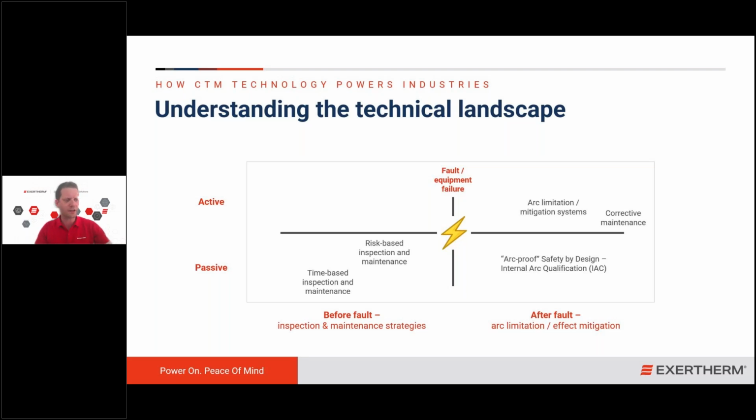And here the discussion circled around the main physical causes for arc flashes. On the one hand, continuous partial discharge sensing, especially on the medium voltage and high voltage side, for identifying any noise or any activities going on before the strike would break through.